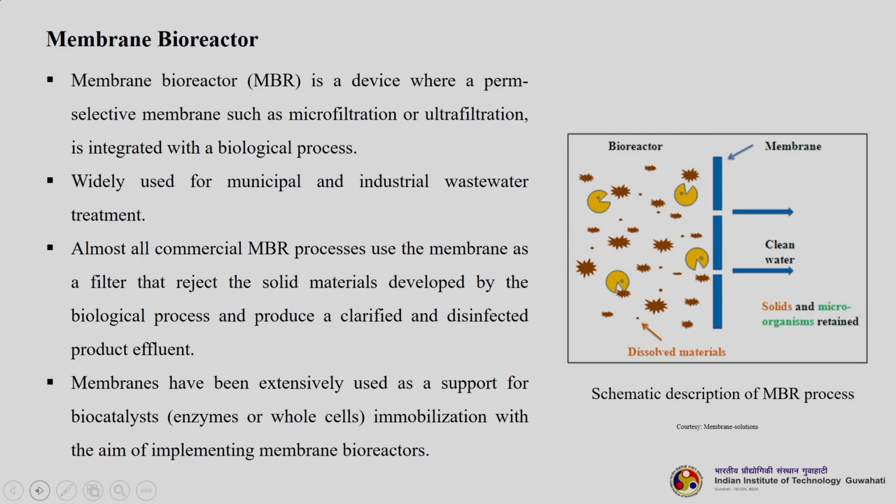Now, let us discuss a little about the membrane bioreactor. A membrane bioreactor is a device where a perm-selective membrane, such as a microfiltration or ultrafiltration membrane, is integrated with a biological process. In a membrane reactor, the chemical reaction and separation happen inside the membrane module, and here the membrane contactor is basically coupled with a biological process. It is widely used for municipal and industrial wastewater treatment.